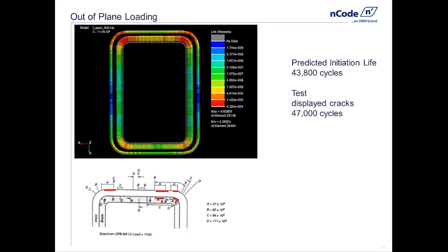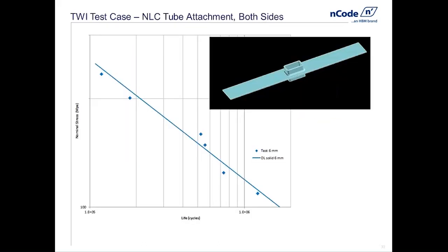There are a couple more examples from the Weld Institute report. This one happens to be a continuous horizontal plate, and the 2 tubes that you see welded, top and bottom of that plate, are non-load carrying. So the load basically is transmitted through that horizontal plate. Those tubes only interact with that plate in terms of stiffening it. So basically, it's an attachment that's non-load carrying.